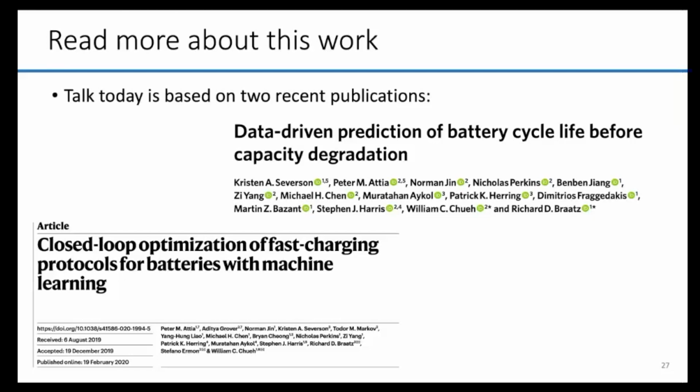When you applied the lasso to the cycle life prediction, did you use any method to smooth the noise of the training data and test data? If yes, what kind of method did you use? We did do a linear interpolation of those voltage capacity curves such that they were sampled at a consistent step in voltage. The details of that are available with the data set. I'm not recalling them offhand. And then there was some kind of analysis looking for what I would call gross errors in the capacity. So if we saw very, very large jumps, we went ahead and threw that data away because we are relatively confident that that's not physical, that's measurement noise.